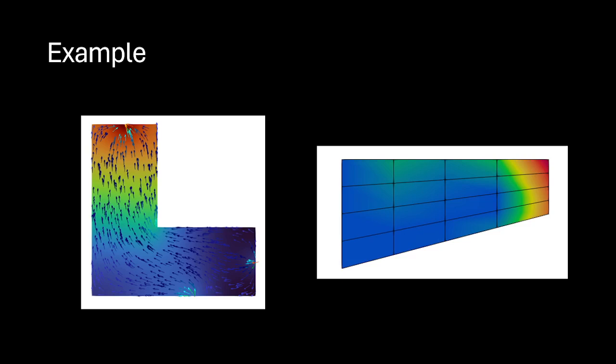So these are two examples of the finite element method. This first one is a structural problem, a cantilever beam, where this portion is fixed and one UDL force is applied over here. You can see the deflection data here, and the domain has been divided into 16 pieces and assembled into the whole domain.